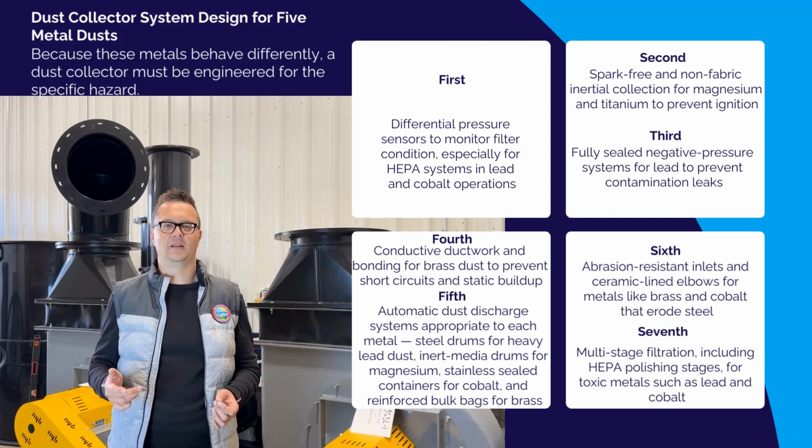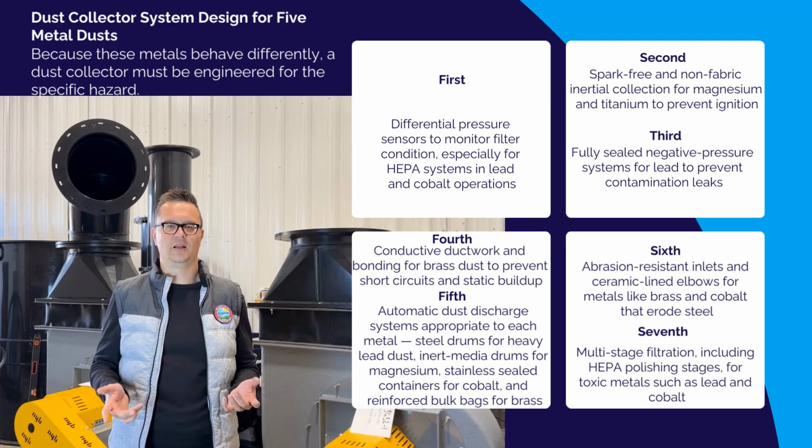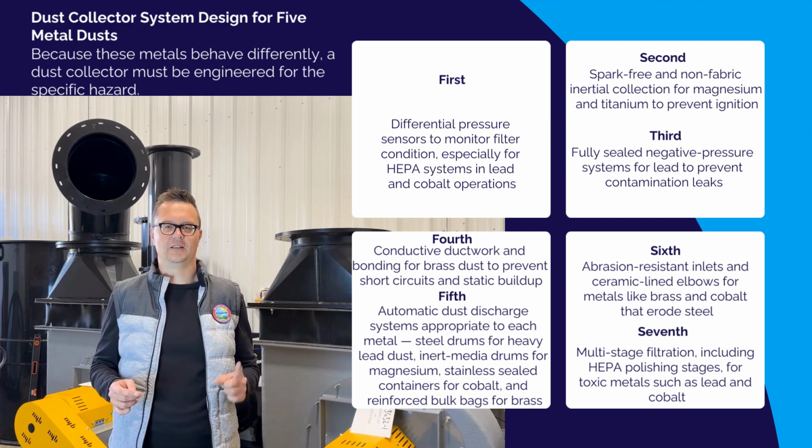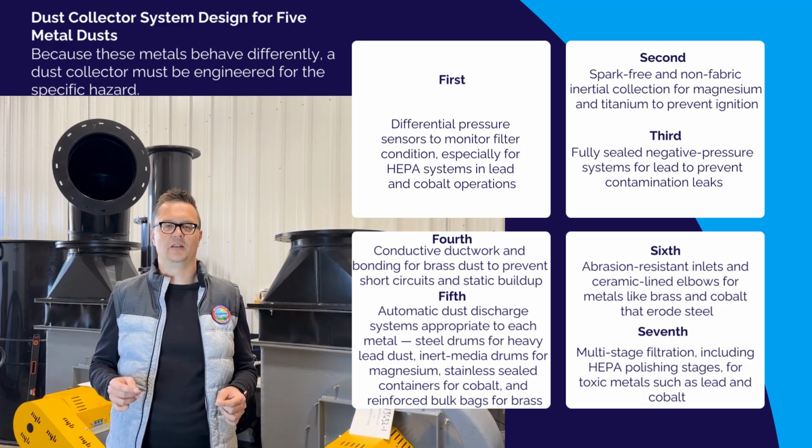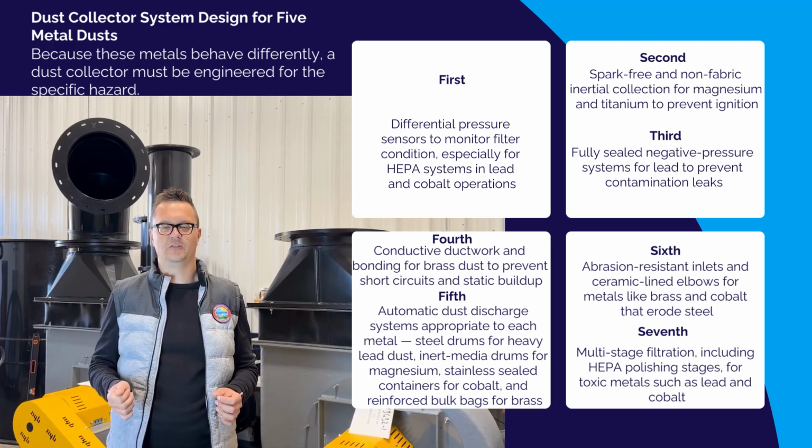Fifth, automatic dust discharge systems appropriate to each metal, steel drums for heavy lead dust, inert media drums for magnesium, stainless sealed containers for cobalt, and reinforced bulk bags for brass. Sixth, abrasion-resistant inlets and ceramic-lined elbows for metals like brass and cobalt that erode steel. Seventh, multi-stage filtration, including HEPA polishing stages for toxic metals such as lead and cobalt. This is not one universal solution. It is 5 different engineering systems living inside one integrated design philosophy.